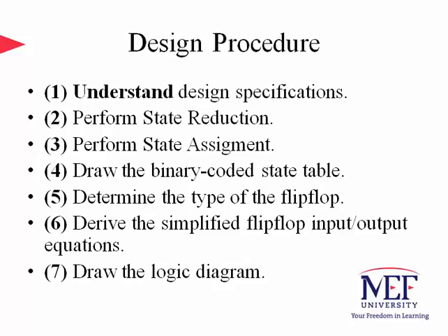Let us summarize the design procedure in this slide. By my count, there are basically 7 steps to go through when we design a sequential circuit. To some designers, some of the steps could be merged. I won't object to that. First step is to understand what the circuit specification is. This could be your boss telling you what you need to implement. In other words, we read the word description that's provided to us to learn what we are supposed to design.